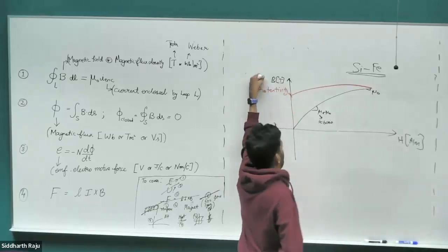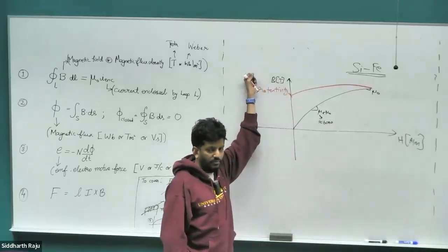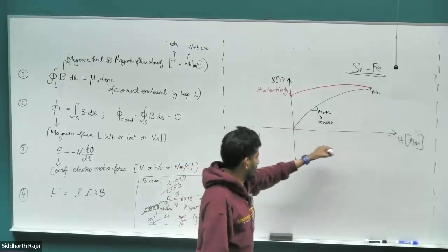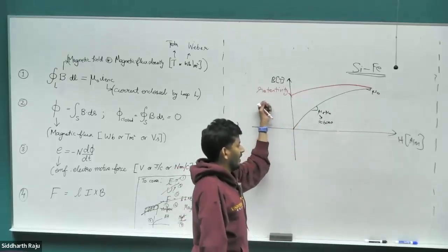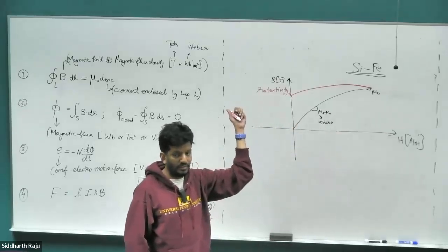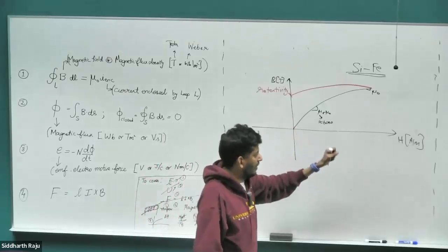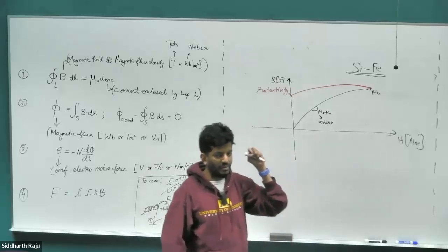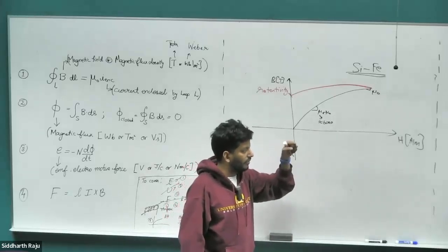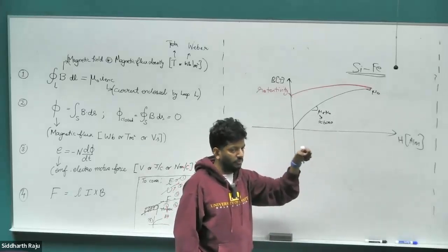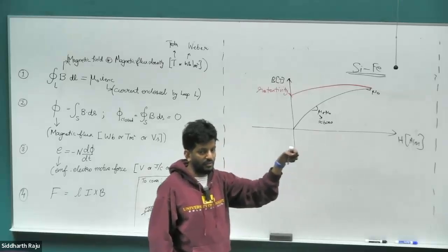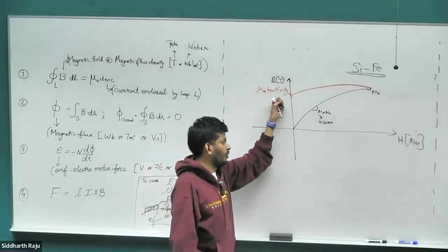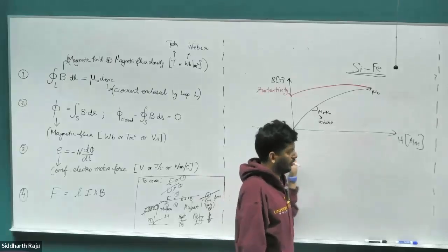Basically, whatever magnetic field is retained is residual magnetism. So once you make the current go all the way down to zero, it still retains some magnetic field. This is what happens to magnets, right? When you take out all the magnetic field, some of the domains still do not get knocked back off. They have been embedded to a good extent, so they retain their orientation and the magnetic field that was imparted to them, and they don't go down to zero once you make the H field go all the way down to zero.